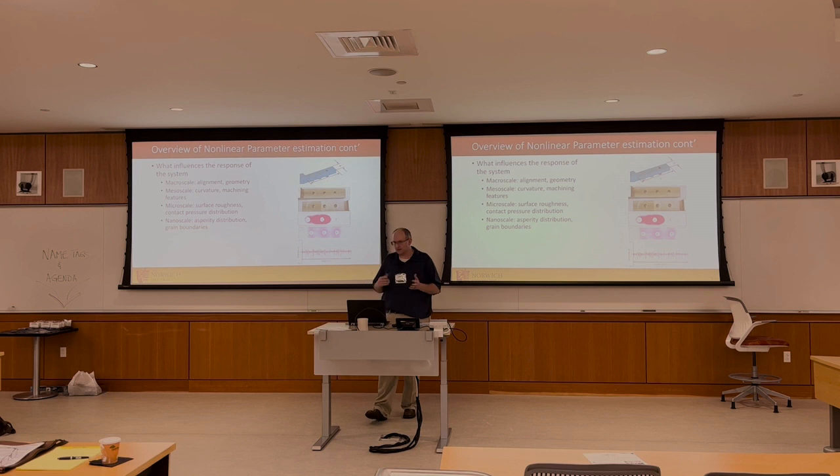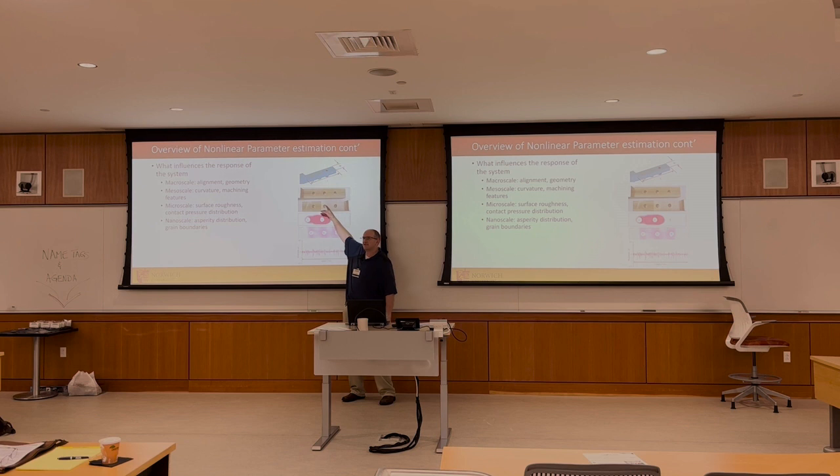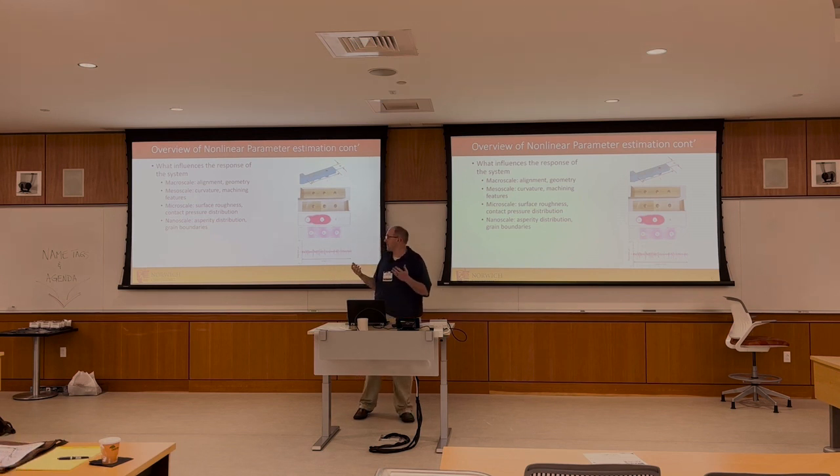So just overall, some things that are important for me to take into consideration is the overall shape of the nonlinearity when machining. This is actually a beam that we were testing with at Sandia. The wire EDM actually snapped while it was cutting, and then they can replace it and continue cutting. If you run your finger over this beam, you don't feel it, but it's visibly there. And at the end of the day, it actually turned out that you can see it on what's called the pressure, the contact pressure. So how everything sits together.